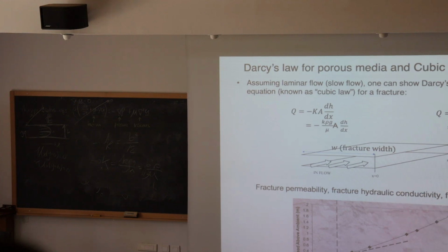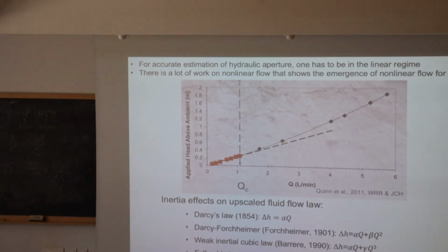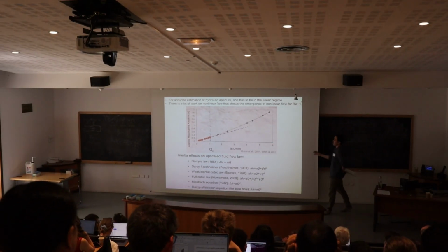So why is this practically important? Because if you go out to the field and blindly do a pumping test, you could very easily be in this regime. What people do is use just one data point and apply the cubic law, and then you can very much underestimate your hydraulic aperture. So the understanding of the linear flow regime to the nonlinear flow regime has been of large interest, and it has been studied a lot.